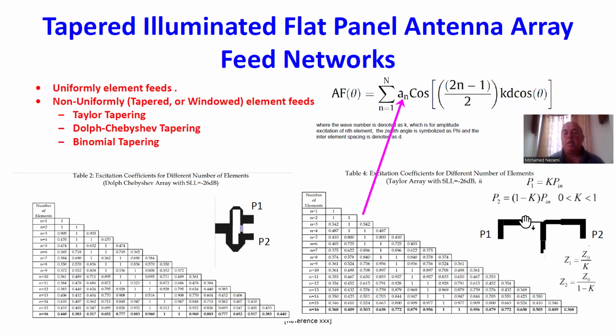We use these unequal power splitters, either unequal T-junction or unequal Wilkinson divider, and we're going to have equations for these so that, depending on the power ratio between these two outputs, we can find out what this width has to be. Okay, and likewise for the Wilkinson as well. We have the equations for those, and we will have one session on this.